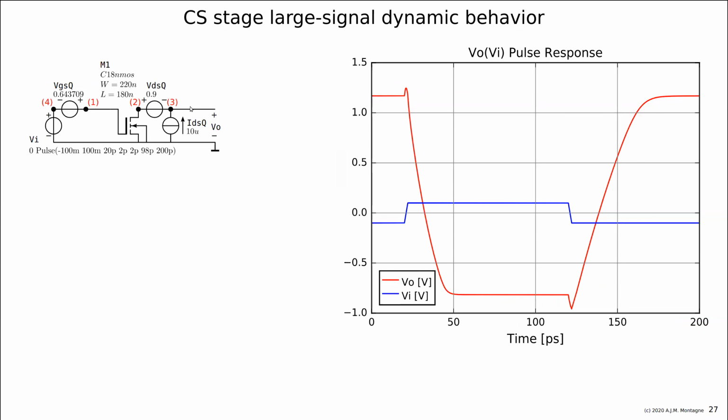So the source, of course, is delivered by the 10 microamp current source here, because if the transistor goes off, the bias source of 10 microamp delivers the current. And the sink is delivered by the voltage source, because if the transistor goes into conduction, if the resistance drops, then this one can cause more current through the load, and the load also has its own internal capacitance, of course.